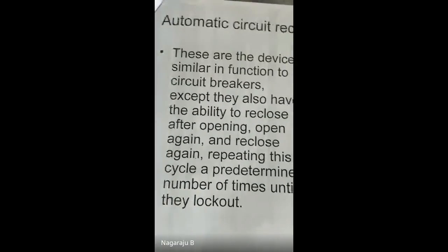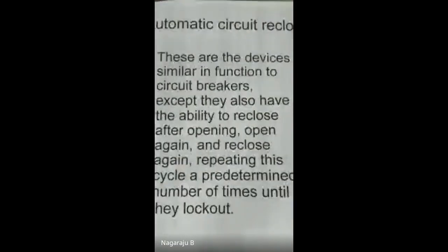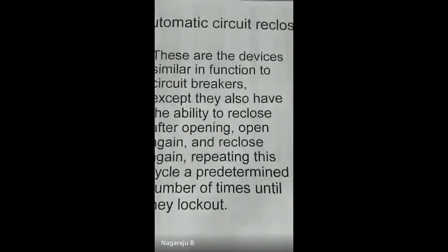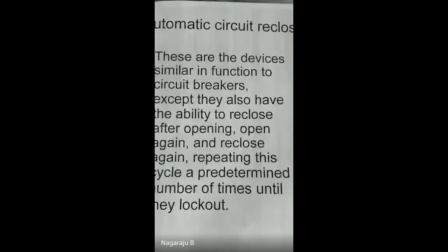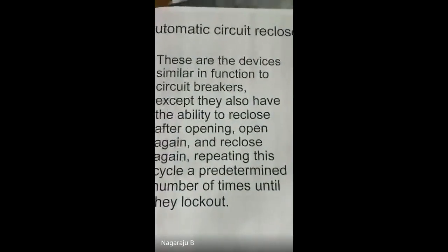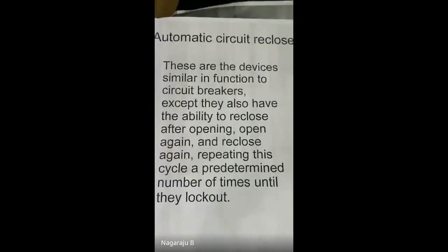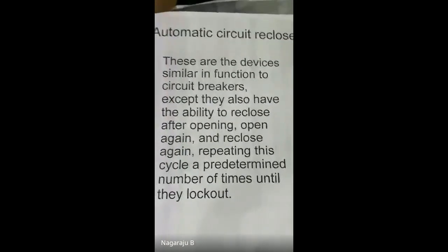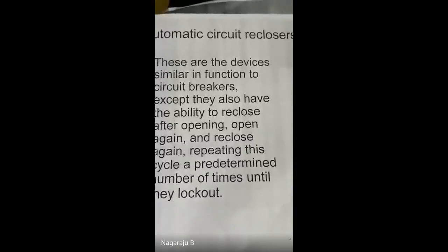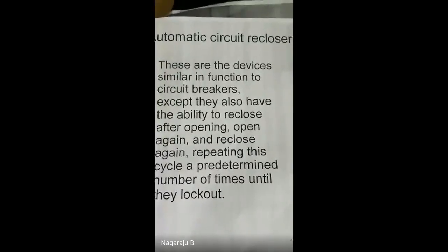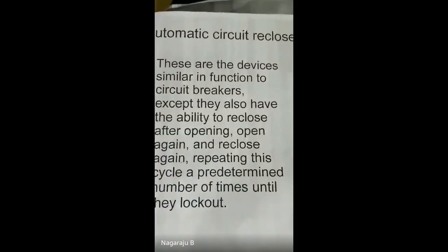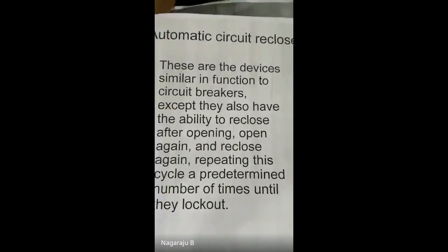This recloser can be set for a number of different operation sequences, such as the first: two instantaneous operations, where one is a trip and another is a reclose, followed by two time delay trip operations to lockout.